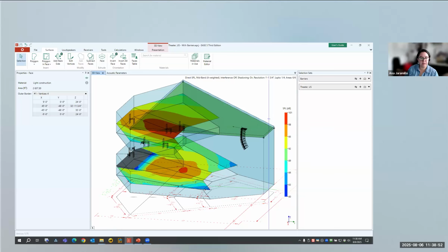And with the move command, it works the same way. You can enter the direction and the distance. The difference is that just moving, of course, doesn't create those side faces that have been added in this case. And per Joe Bridges' question before, if you just move it or displace the face, it doesn't drag the ends of those faces that are, in this case, the walls. For previous EASE 4 users, that was the case. If you displace a face, it will drag everything that's connected to it. It is not the case in EASE 5.